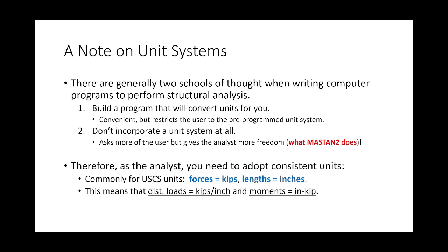Okay. So as the analyst, you need to adopt consistent units. And my suggestion to you is to use forces in kips, lengths in inches. The reason is so that your displacements at the end come out in inches, and most of your loads are defined in kips anyways. So when you define distributed loads, they need to be in kips per inch. And whenever you look at moment diagrams, they're going to be in inch-kips. That doesn't matter today, but it'll matter on Wednesday.